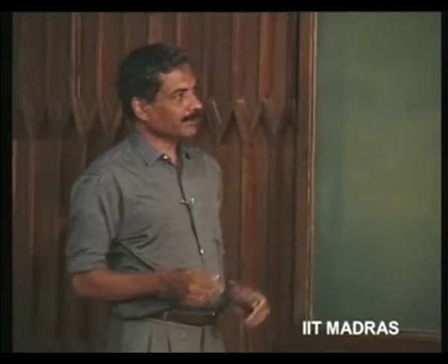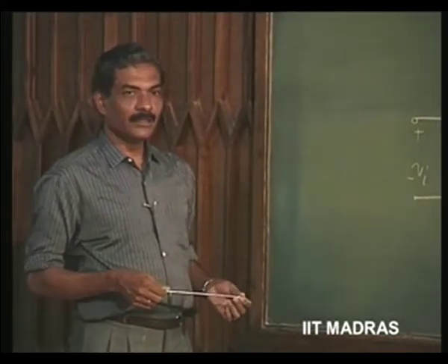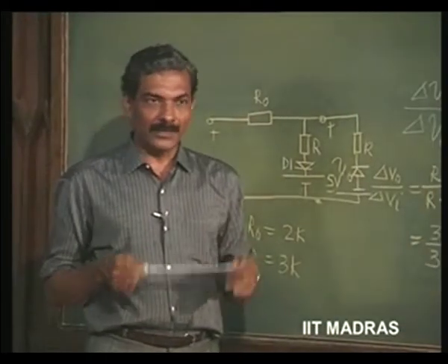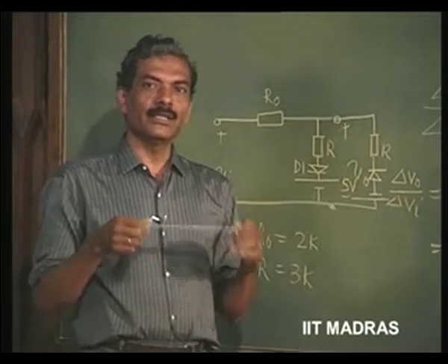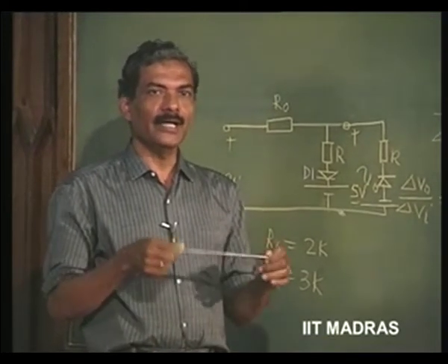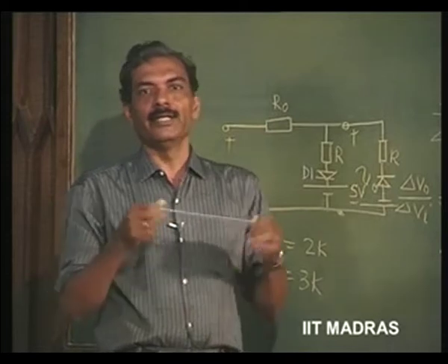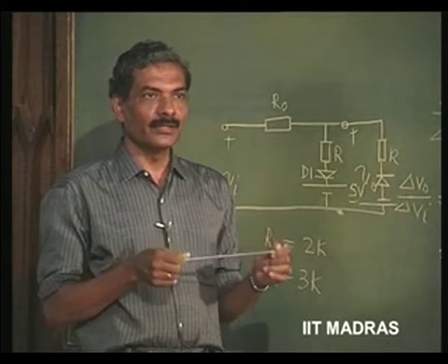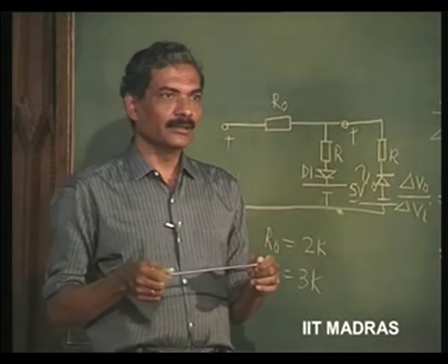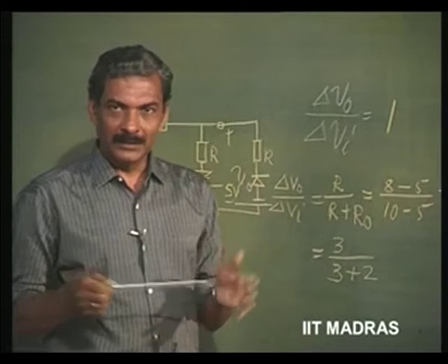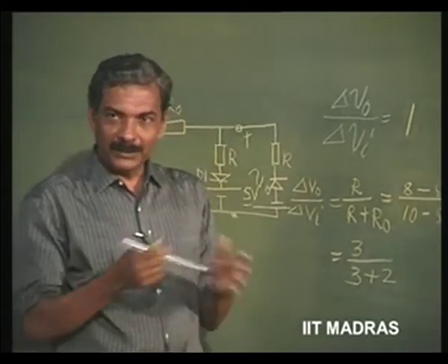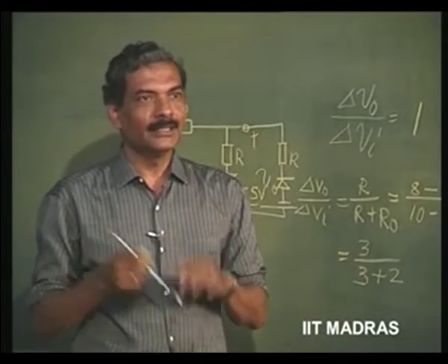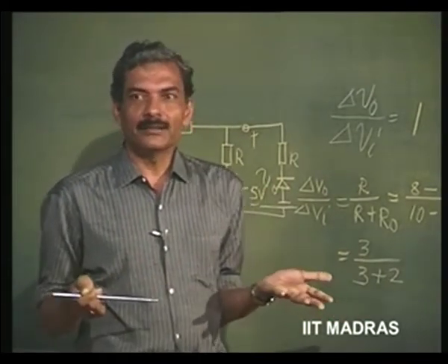In the next session of our lecture, we will be using the same concept of diode function generator, but we want to convert a sine wave into a unidirectional sine wave. Again, this is also a diode function generator with some kind of slope changing. Output should be 0 when the voltage is negative, and output should be equal to input when the voltage is positive, that is all.